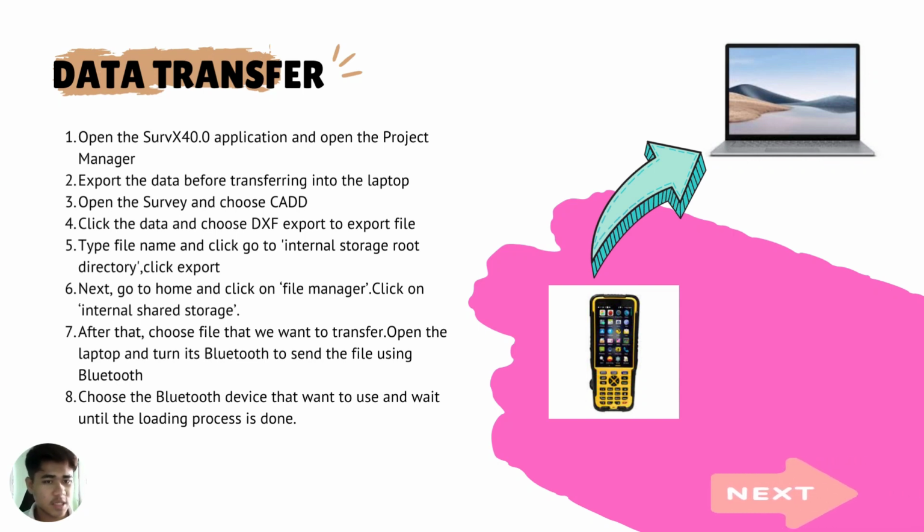Export the data before transferring into the laptop. Open the survey and choose CAD. Click the data and choose DSF export to export file.